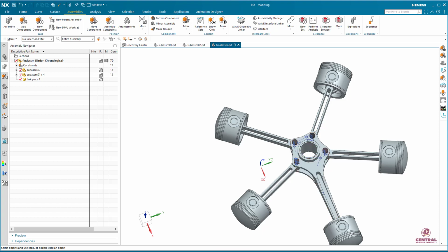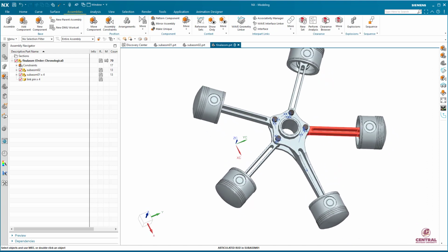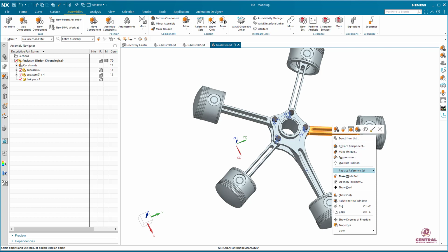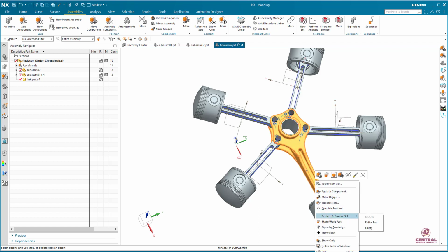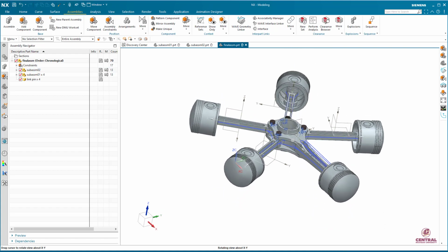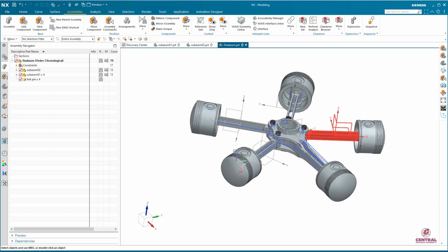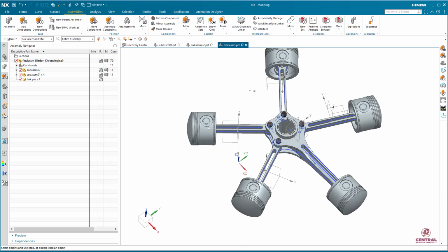constraint, assembly constraint. So to make that angle come out exactly, I'm going to turn on the reference. So since I'm doing one, the other should automatically do it. Same thing I'm gonna do to the master rod as well. There we go. So now we have a plane we can use for angle. So GX plane of each articular rod, and you can see also GX plane of master rod. I can use those for measurement of angle.